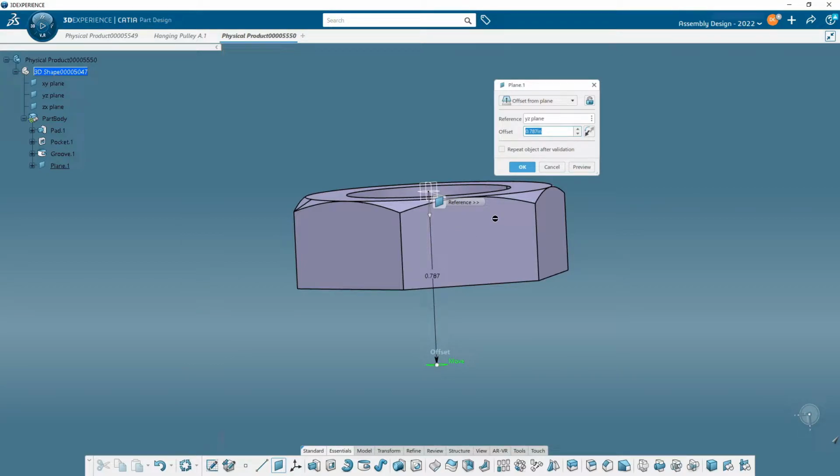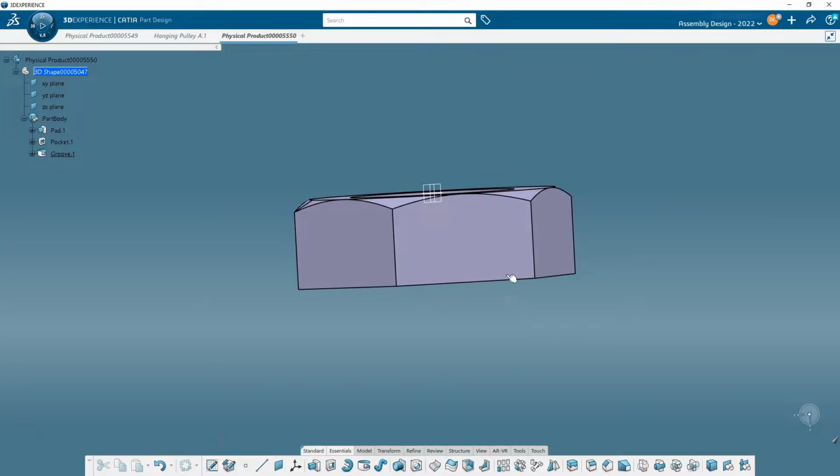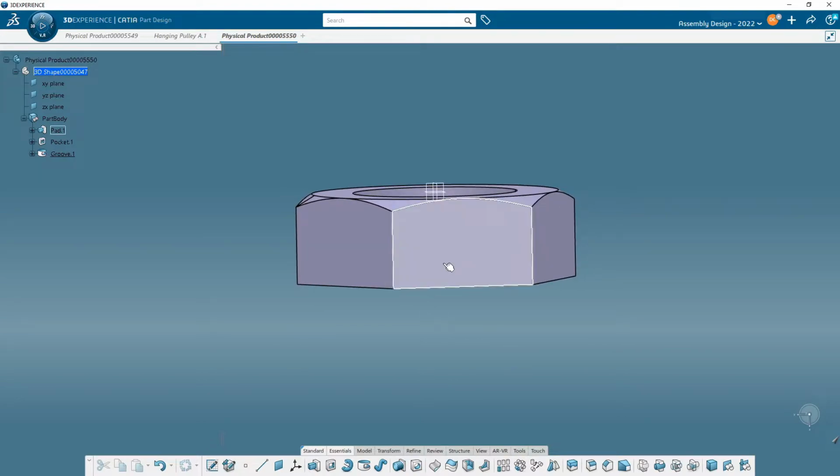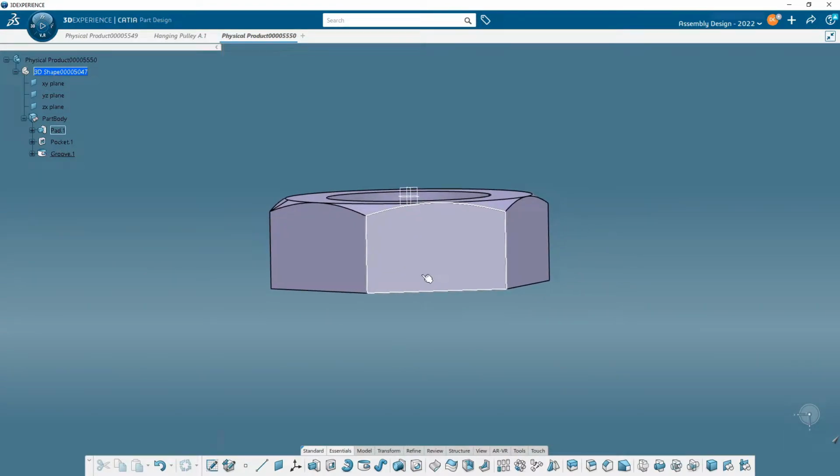By the way, do you guys know what I'm talking about? Why I'm worried about this plane thing? In order to do the mirror, I need to have a plane right here in the middle that's going to allow me to mirror this element perfectly over the middle of this whole length right here to get this to fall right here on this edge. I need it perfect. So I could add a new plane, like I said, or I could go, you know what I should have done is I should have padded this out symmetrical across that mid plane.